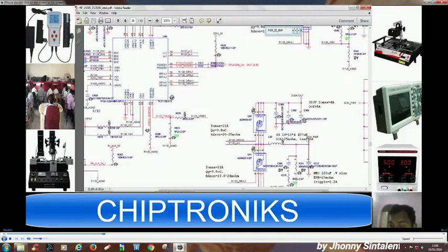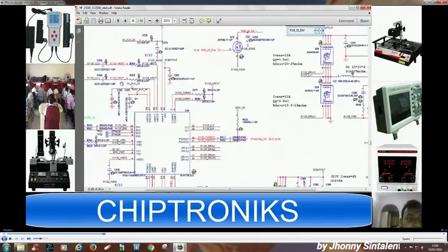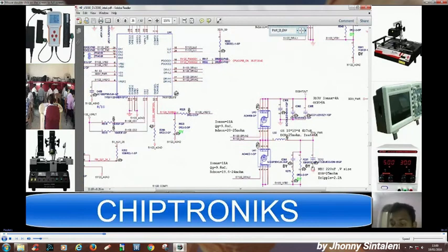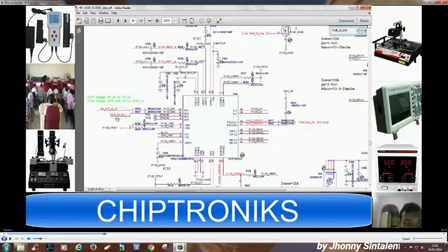So this 3.3 volt is different than this 3.3 volt. This is the LDO volt, it will get out directly, whereas this 3.3 volt would come after switching this MOSFET. So how would this MOSFET switch? It must get a gate signal, and this gate signal would come when this enable 2 would come, and we have already checked that this signal would come from where?